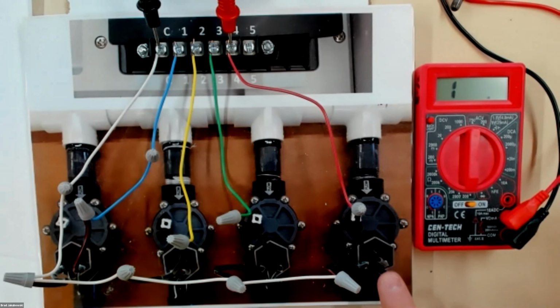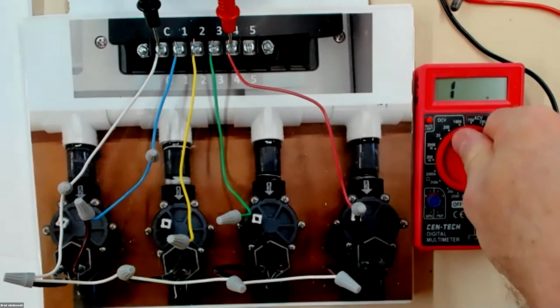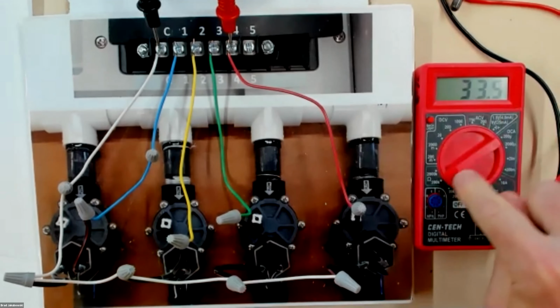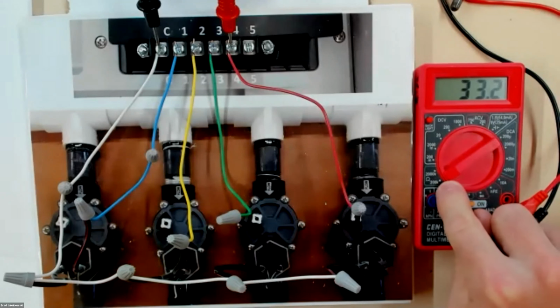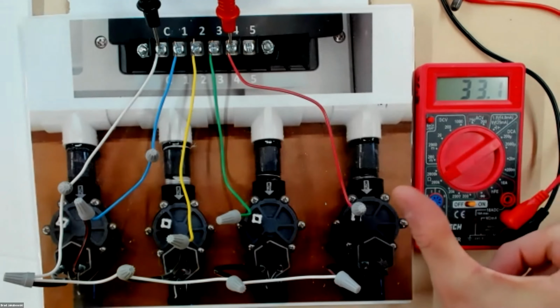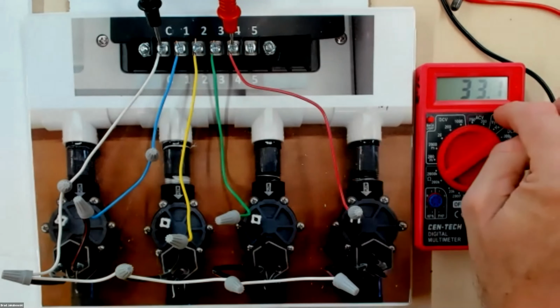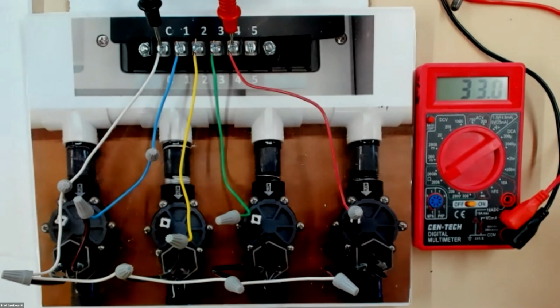Now, it could be another thing if you actually happen to be working with some golf course guys or with some Toro solenoids. They have a solenoid called a spike guard solenoid that is rated at 33,000 ohms instead of just 27 ohms. Okay, so what I'd like you to do then is just turn your range to 200,000. And now instead of it reading just from 0 to 200, it's going to read all the way from 0 to 200,000. So what we're reading here then is actually about 33,000 ohms.